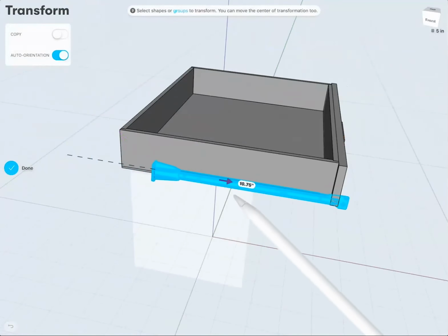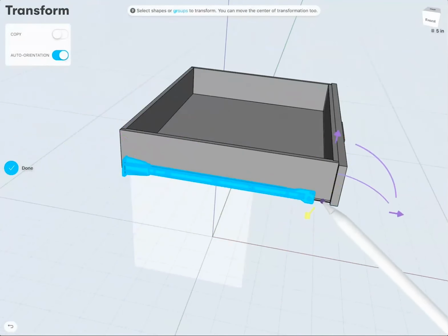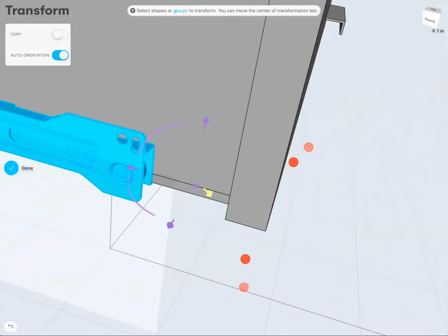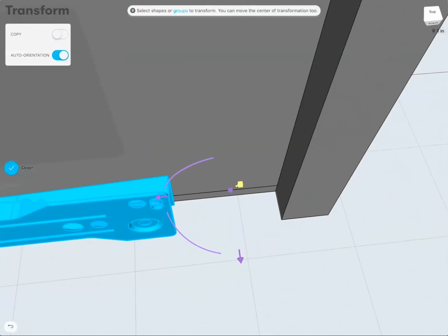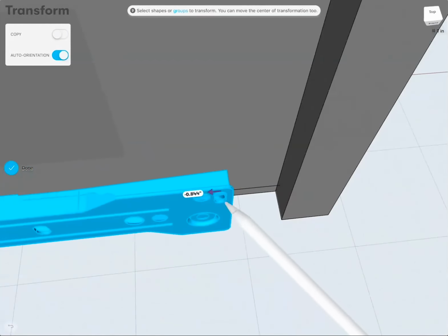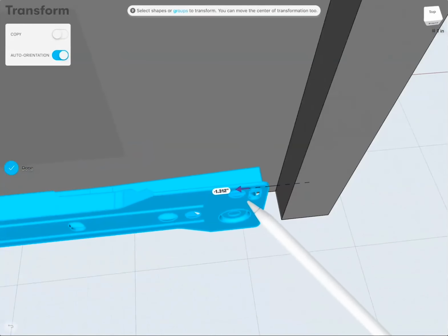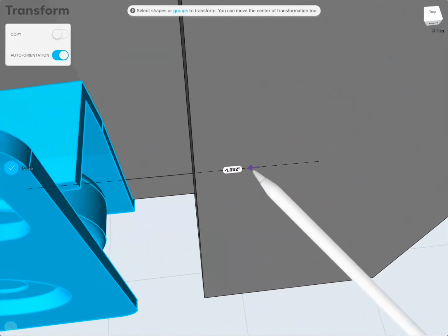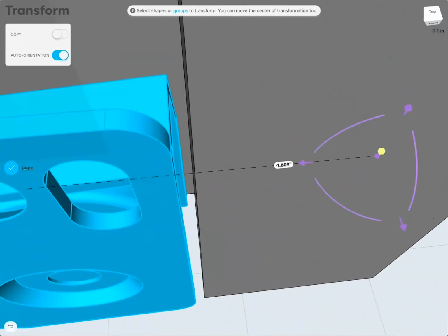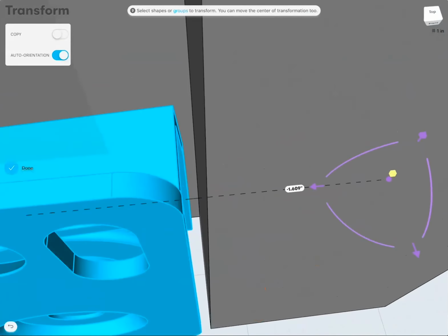And then we just move it to there. I bring my widget a little bit closer. And here's another tip when you adjust these parts. Right now you see the steps, how it's moving, and the more you zoom in, the finer the grid, and the finer the steps you will be able to position these parts.